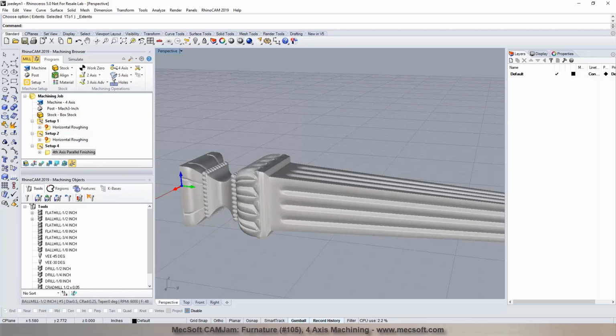Right. But then you have other ways to efficiently go back and just program those areas by just defining boundaries. Got it. Yeah, I see that. So you don't have to machine the entire part. You can just create a small boundary for that section. You can either do the drive surface machining, like we talked about, or you could do an indexed machining where you just throw in a boundary and then use a 3-axis operation. Okay. You can also rotate it to like a 45-degree and then machine it if you have undercuts in a different location.